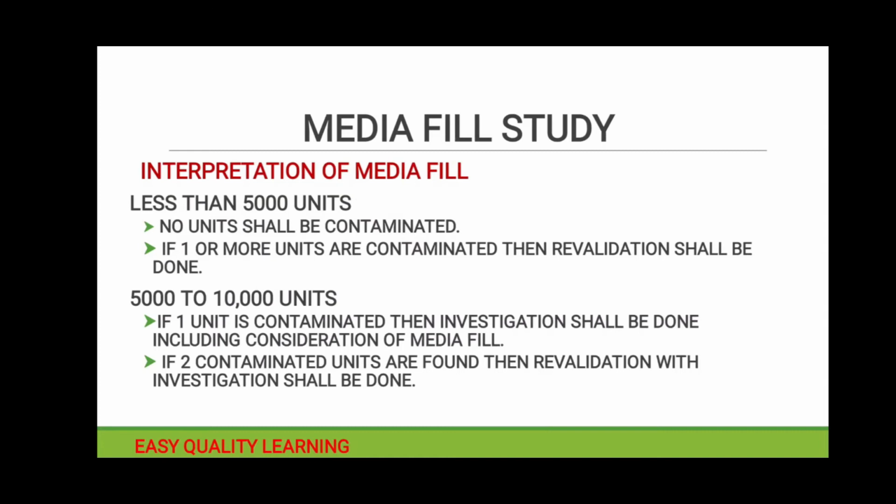Then interpretation of media fill. If you are filling less than 5,000 units, then no unit shall be contaminated. If one or more units are contaminated, then we need to do revalidation for the media fill activity.